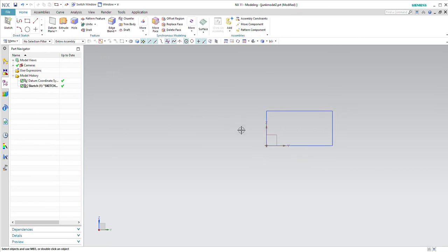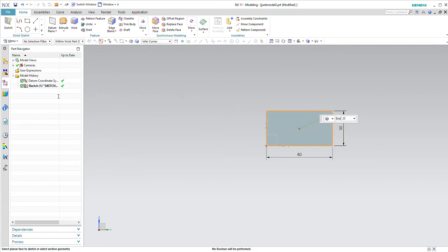Now I want to turn my box into a beam, so I'm going to extrude it. So I can choose extrude over here. I could choose revolve. If I revolve this, it would make like a puck-like shape. But I'll do extrude. It wants me to select the curve. I'm going to select this curve, and then I can specify the size, and it lets me do positives and negatives for the distances. It's just relative to the position that it's in.